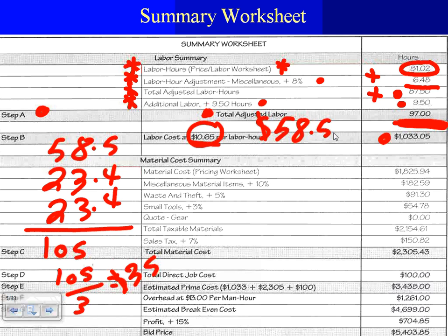Now some people take this number, the 35, and double it. Phil, you double it, it becomes 70. That includes your overhead and your profit, and you bid the job at 70. 78, you can start playing with that number. Because remember, this is just your cost, not including your profit or your overhead, your project manager, you working with the project taking off, that's not included here.